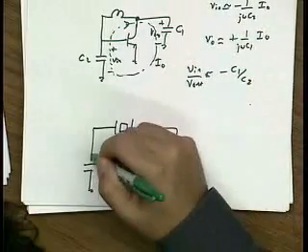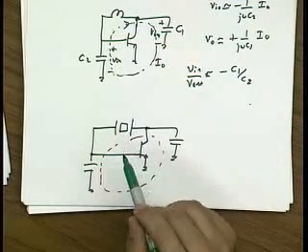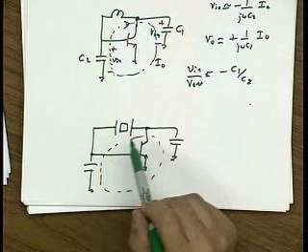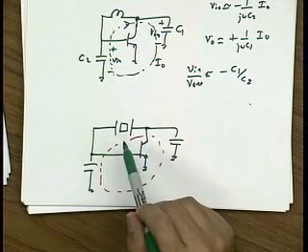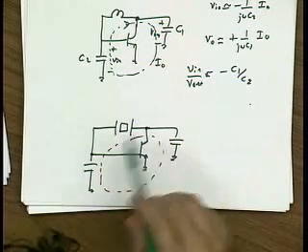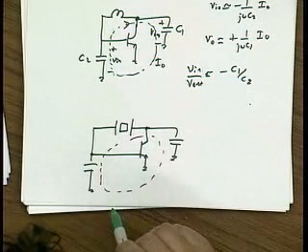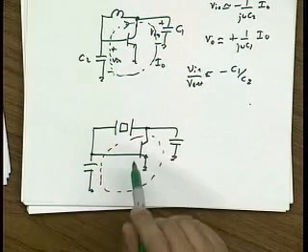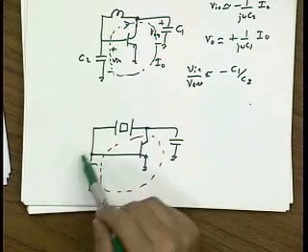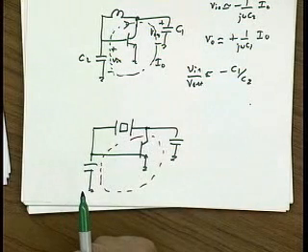That means that you have to be really careful that when you build a circuit, you don't DQ the crystal. Right? And that, in essence, dictates what topologies you would or would not use. So the Pierce is basically a grounded emitter. Think about a grounded collector or grounded base, and you'll find that both configurations will actually load the crystal with the transistor impedance. So we pick the configuration that has the least loading effects on the crystal.